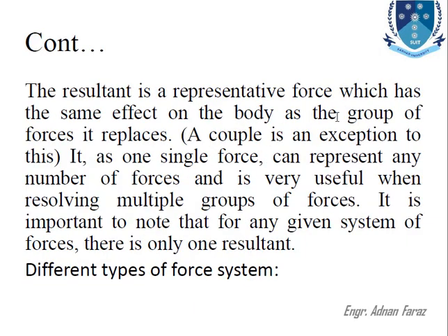The resultant is a representative force which has the same effect on the body as the group of forces. Resultant is basically the representation of all forces acting on a body. One single force can represent any number of forces, and it's very useful when resolving multiple groups of forces. It's important to note that for any given system of forces, there is only one resultant. Whichever system you want to use, there will be only one resultant.